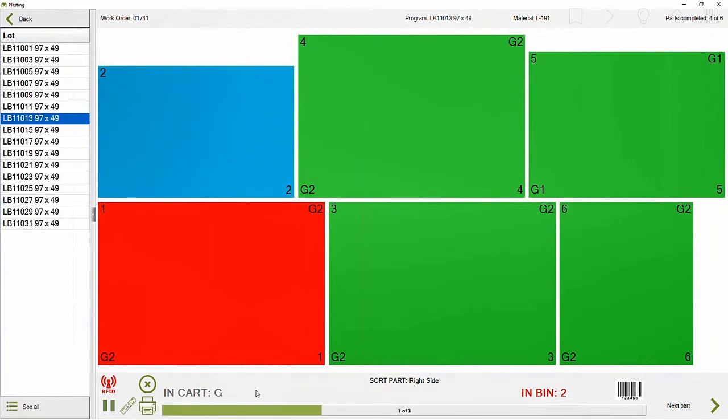So we can group the parts by color of edge banding, or group the parts by types of part, like all the bottoms, the tops, the thick shelf together, or all the sides together to regroup in another bin. So we're allowing the operator to know how to group the part when it comes out of that machine without him having to look at every part and knowing where to go.